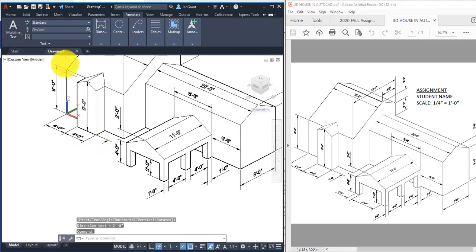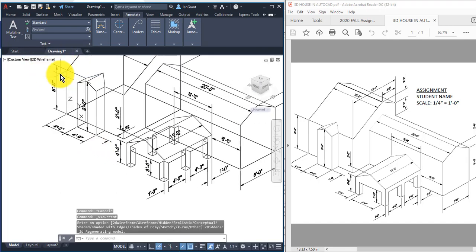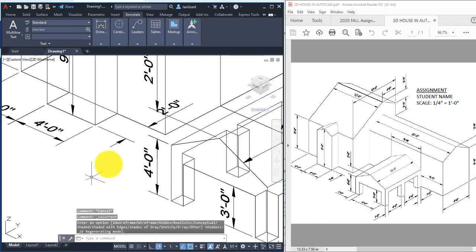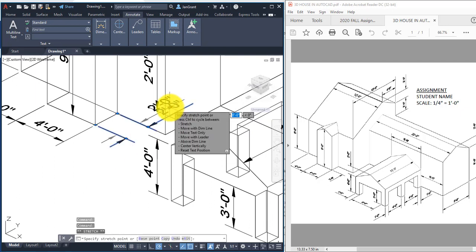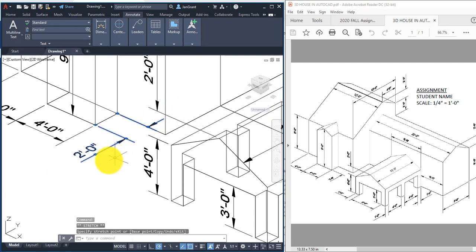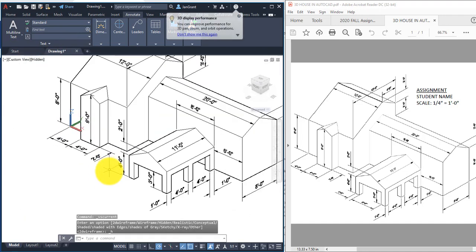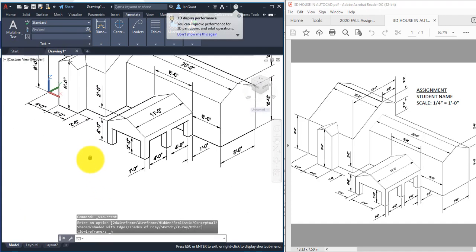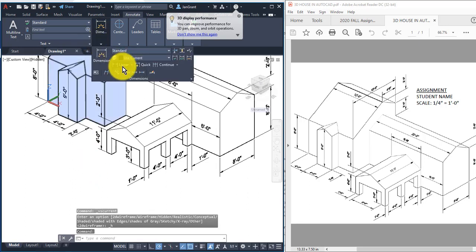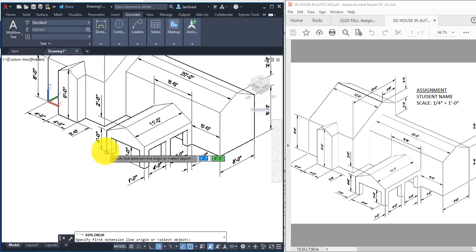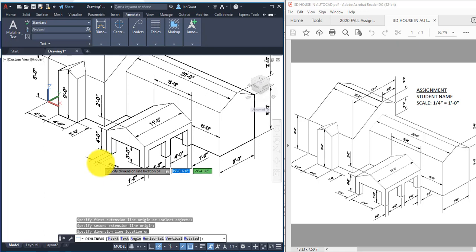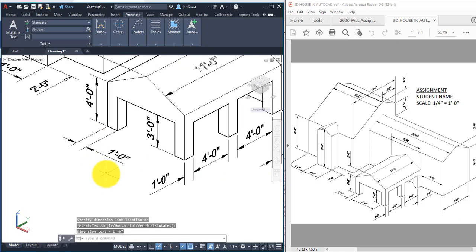I placed it, and then I'm going to change this to 2D wireframe, so I can come in here and grab this 2 and bring it out, because it was buried from the hidden view. So I just went to 2D wireframe and got that. Now I'm going to take a chance here and see if these can also go, they should be able to, yeah, along that bottom edge. Looks like this one needs to be pulled over here with the grips.